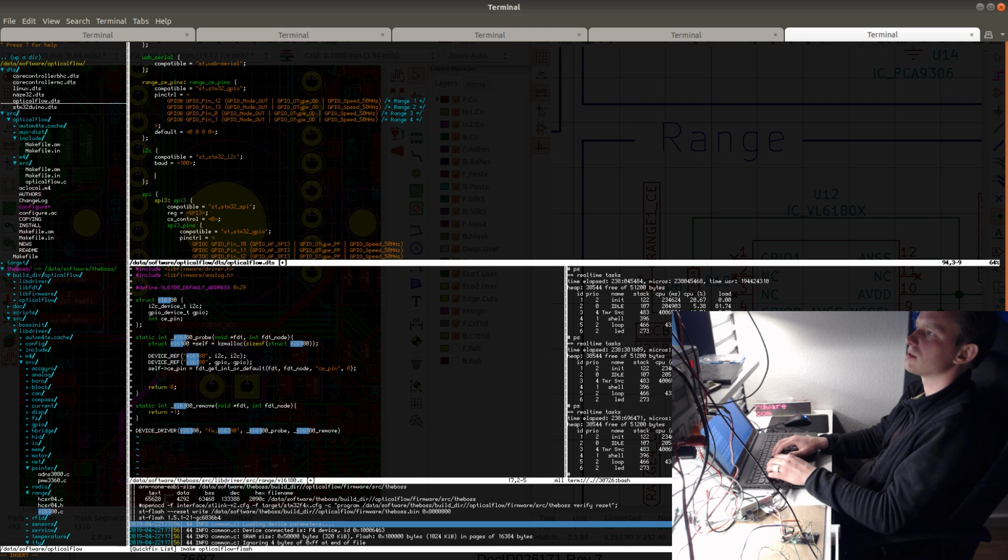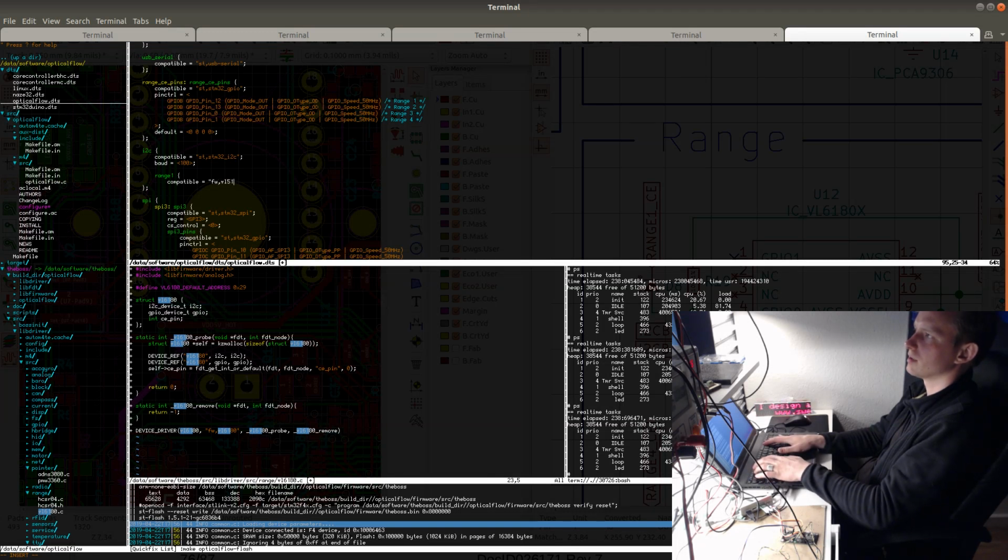Then I'm going to create all the sensors here. So we'll have range 1, compatible, and this is going to be handled now by this VL driver. So it's going to have a compatible string that looks just like the text you can see there in the device driver definition. So firmware VL6180, and let's see, I2C is going to be...